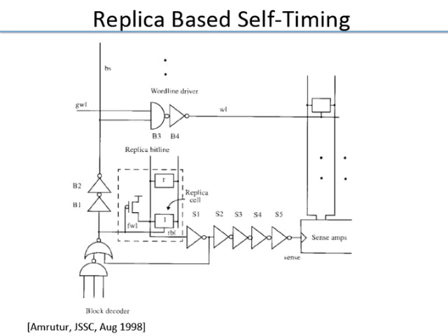And the memory cell, as we discussed in the last lecture and before, is done by the foundry. It's very custom designed, and they might even violate some of the design rules in those places. So it's very hard to mimic it with just logic gates. It's better to use a copy of a memory cell in your path.